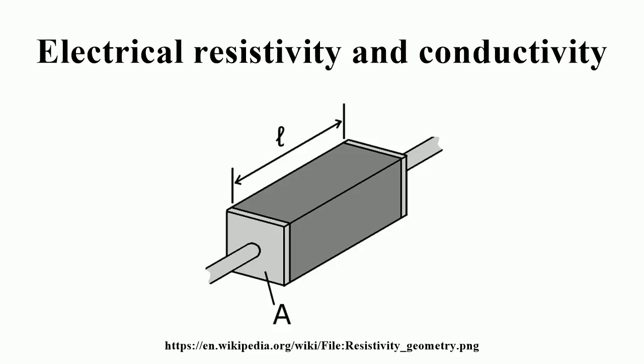There can be many such energy bands in a material, depending on the atomic number of electrons and their distribution. The material's electrons seek to minimize the total energy in the material by going to low energy states. However, the Pauli exclusion principle means that they cannot all go to the lowest state. The electrons instead fill up the band structure starting from the bottom. The characteristic energy level up to which the electrons have filled is called the Fermi level.